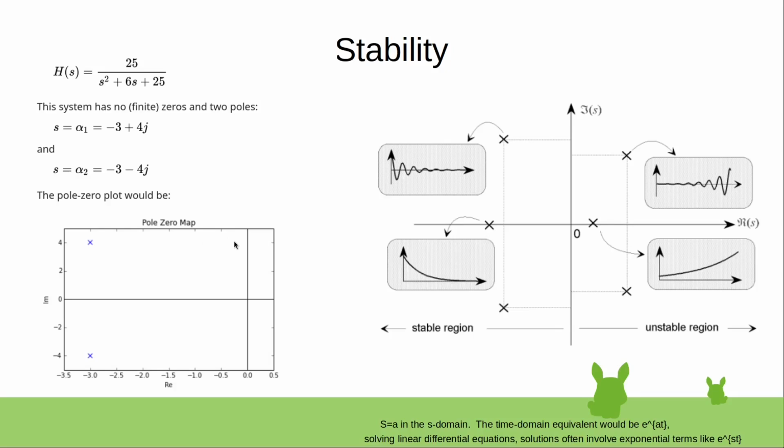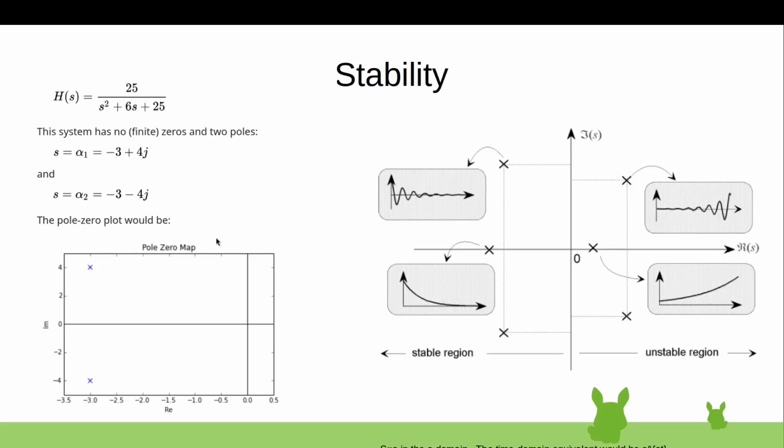And when we consider the dominant poles on the imaginary axis, then the system will not decay to zero, but it will not go to infinity either. It'll just stay stagnant, either with or without frequency. And if the dominant poles were to the right of the imaginary axis, then the system would actually go to infinity over infinite time. Well, what would that all even mean?